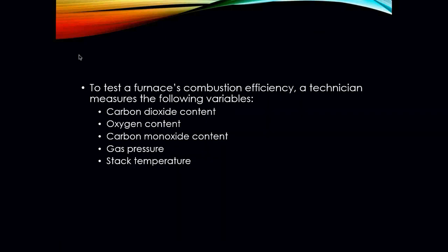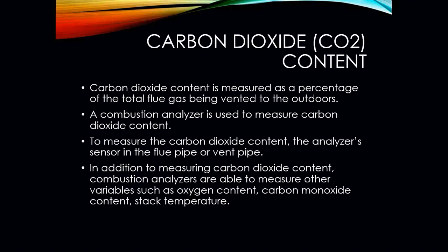To best test the furnace combustion efficiency, a technician has to take a couple of measurements and a couple of variables in order to see how a piece of equipment is actually operating. We need to take into account its carbon dioxide content. We need to do oxygen. We need to take a carbon monoxide reading. We need to also take gas pressure. And we need to check the temperature of the stack or flue pipe.